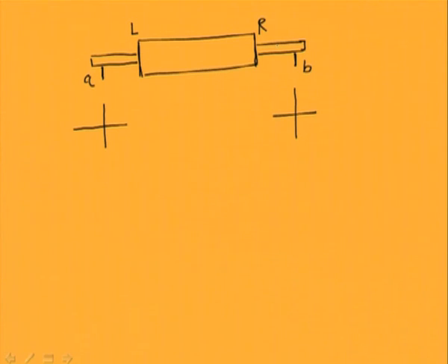Let us say we rotate this rotor at a certain RPM, and because of this there will be some vibration measured at the A and B locations. This vibration is because of the residual unbalance present in the system, which we want to balance.